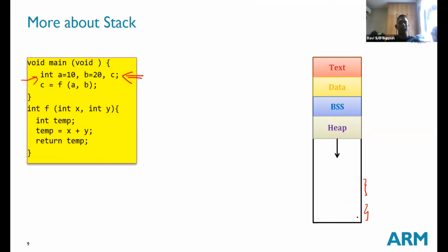How the stack behaves, I think you are probably studying it in other modules. Different processors have different ways of dealing with their stack, correct? Basically it's push and pop. But whether you put the data and then increment based on the current stack pointer, or you increment or change the pointer and then put in the new data, it varies. So different processors implement the stack a bit differently, but the idea is the same. You have a standard storage space and then you push and pop from it.